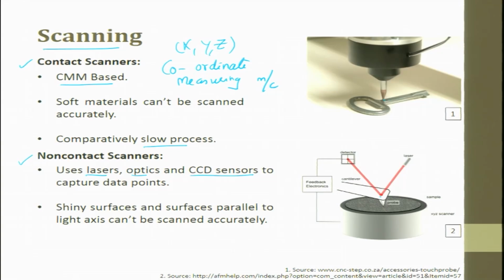The laser hits the backside of the probe. The moment the probe moves up and down, the laser also moves up and down, and this is detected by a photodiode. This photodiode moves in the left and right direction, and it gives you a voltage. Now, the feedback electronics is used to convert the voltage into linear displacement. You try to get the output.